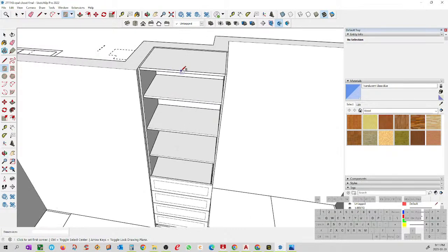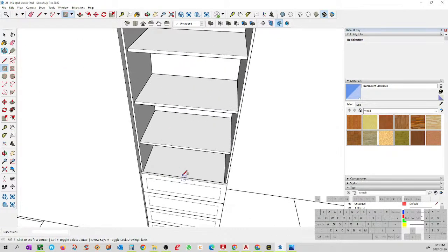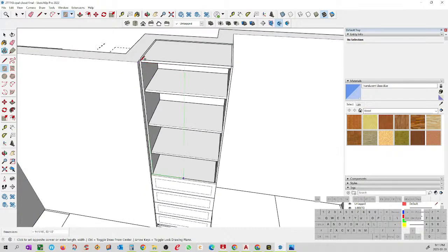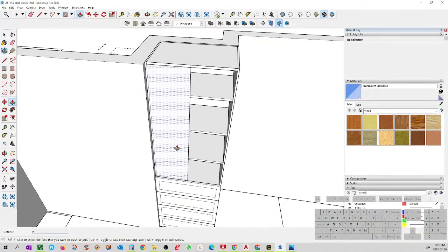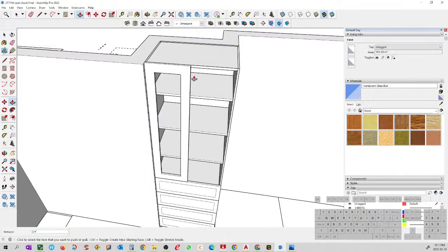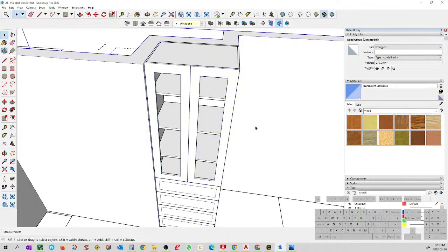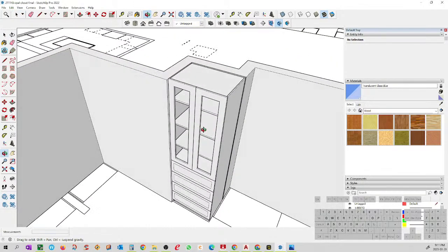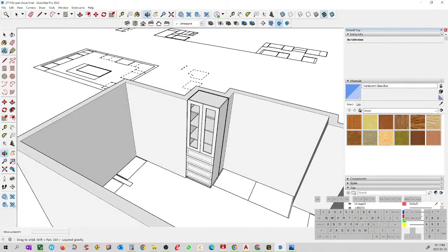All I'm going to add here is two glass doors. The software is very smart. It's giving center points, and it's easy to maneuver. Let's say a 3-inch rail. Make a group. Copy, paste. There you go. So we have 4 drawers, 2 glass doors. That's done.